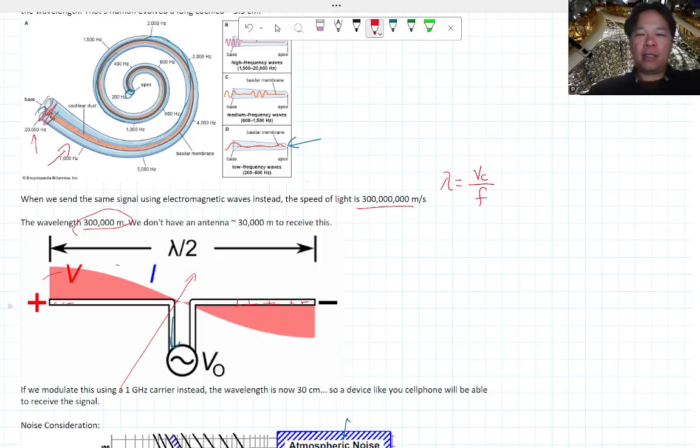And it's this difference on the two sides of the electric field that drives a little bit of current. If you pass that current through a resistor, you get a little voltage out. You want the antenna to be somewhere on the order of the wavelength of that wave, because if it's much smaller, you will not catch the entire amplitude of the electric field that's passing through it. So the smaller your antenna, the smaller the amplitude you're going to be able to catch on your electromagnetic waves.